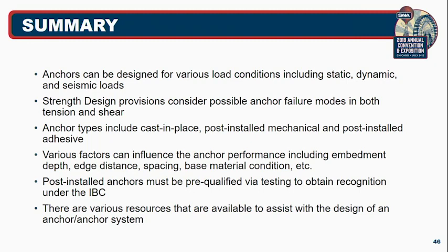Various factors can influence the anchor performance. These include embedment depth, edge distance, spacing, and the condition of the base material. So whether it's green concrete, cracked concrete, thickness of the base material, etc.